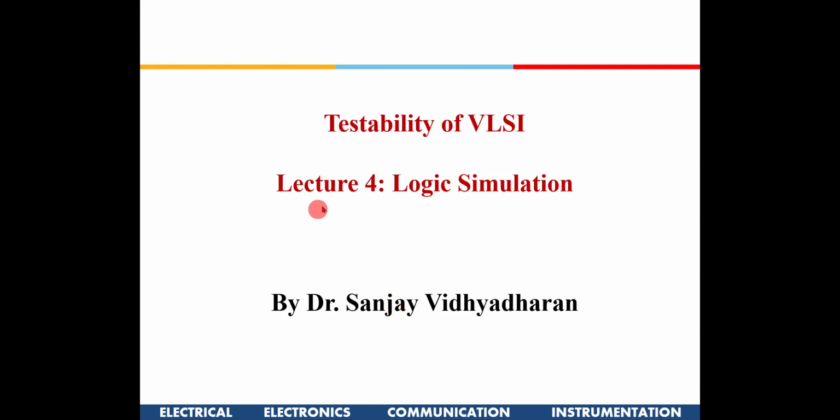Well, good morning to all of you. In the second class, I introduced to all of you the various faults that can be there in a circuit post fabrication. So we discussed that, instead of modeling the defects, it is better to focus on the structural faults, that is stuck-at faults, bridge faults, right? Those kinds of structural faults would be easy for analysis, right?